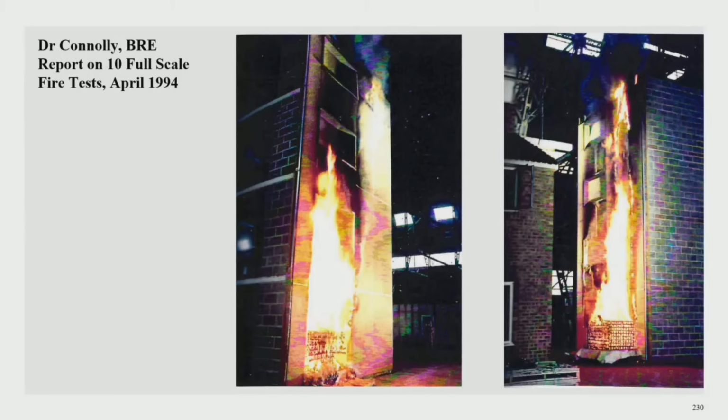Dr. Connolly's 1994 report goes on to detail an experimental investigation into the performance of external cladding systems on exposure to fire. The objective of this particular investigation was to assess the effectiveness of installation of fire barriers in reducing the fire hazard. Non-combustible insulation was used in each test, and 2 types of external overcladding that achieved Class 0, relying on British Standard 476 Part 6 and 7 tests, were installed. The test rig was of a similar scale to Rogowski et al.